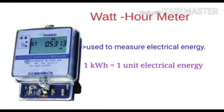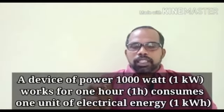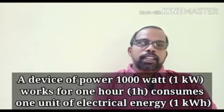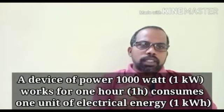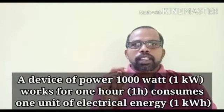The commercial unit of electrical energy is the kilowatt hour, kWh. So what is 1 kilowatt hour? 1 kilowatt hour means if a device of power 1000 watt, that is 1 kilowatt, is used for 1 hour, it consumes 1 unit of electrical energy. So 1 unit of electrical energy or 1 kilowatt hour means a device of power 1000 watt, that is 1 kilowatt, works for 1 hour. Then it consumes 1 unit of electrical energy, that is 1 kilowatt hour.